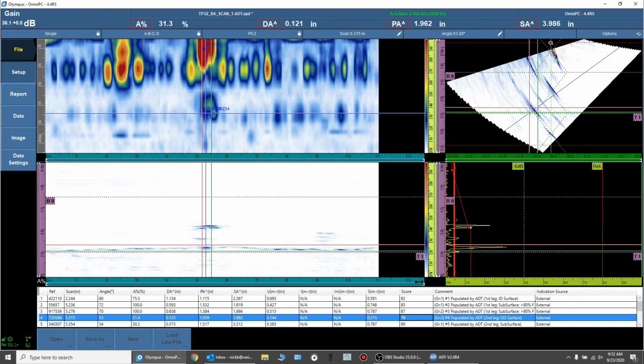And then we've got all of these weld flaw readings that we would normally see in OmniPC. Things like amplitude, length, size, height, start, stop, all those things that help us characterize the defect and apply acceptance, reject criteria. And these are all pre-populated from the raw data, so it doesn't really matter how your technician set up the gate or how you set up the gate.